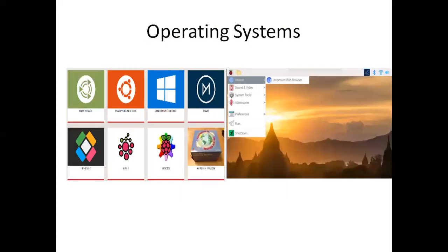As we know, Raspberry Pi acts as a mini computer without an OS. So first of all, we need to install the operating system, and in order to program that, we'll take an SD card and we'll install our required OS. So let us take an example as Linux. First, we need to install Linux in the SD card, and that installed SD card should be inserted into the Raspberry Pi, and then it will work in the Linux operating system.